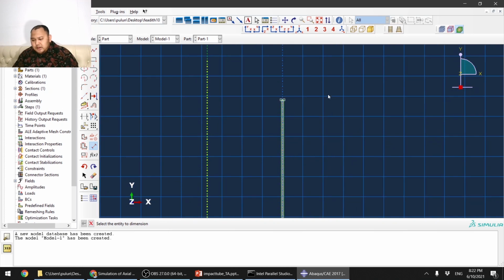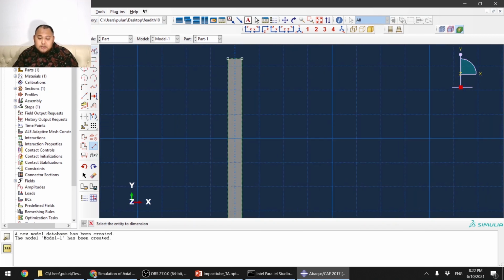And we also need to make the second one here. Okay, so make sure when you create this kind of line, there is an H symbol, meaning horizontal, and then I press escape to escape from it, otherwise the line will keep wanting you to click.